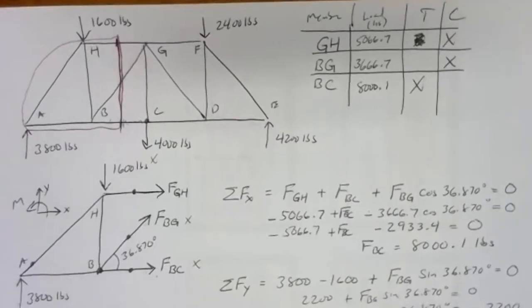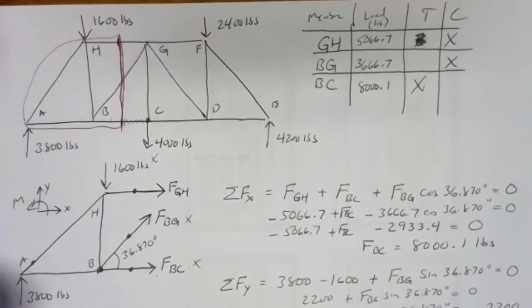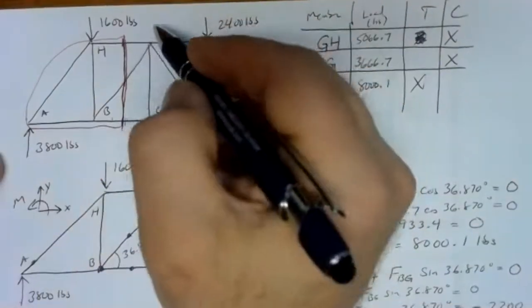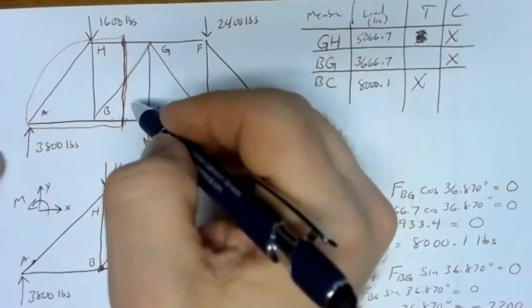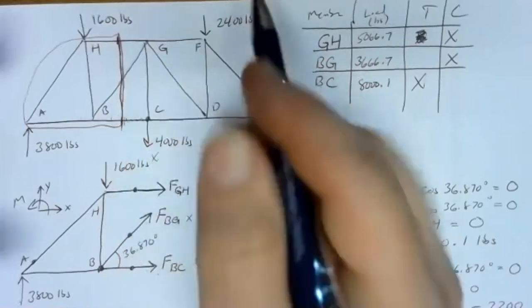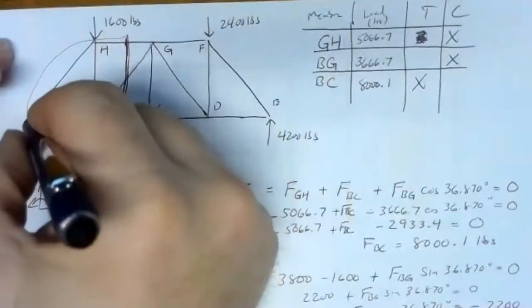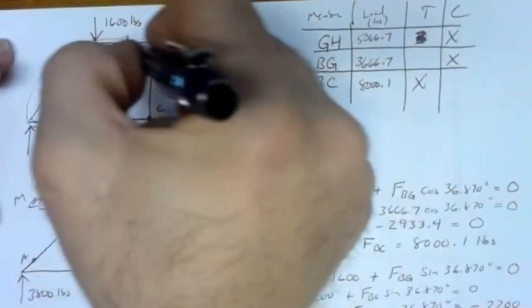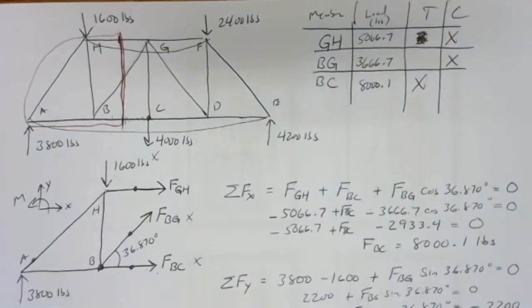Let's look at that on the free body diagram here for a moment. Generally, when you've got a structure like this, and you've got gravitational loads, you've got forces pulling down, weights, generally the structure is going to want to bend kind of like this. It's going to want to bend down that way and bend down that way. Becomes kind of a U shape. It sags in the middle. Well, think about what you know from sheet metal.